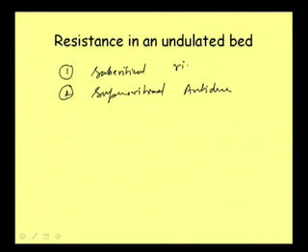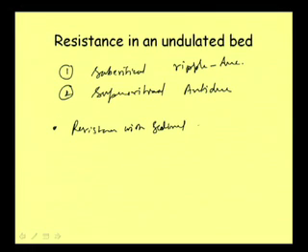And resistance to the flow is higher when it is a plane bed with sediment motion; that also we have summarized. Resistance with sediment motion is almost double that of the resistance without sediment motion. So, that is also one important aspect.